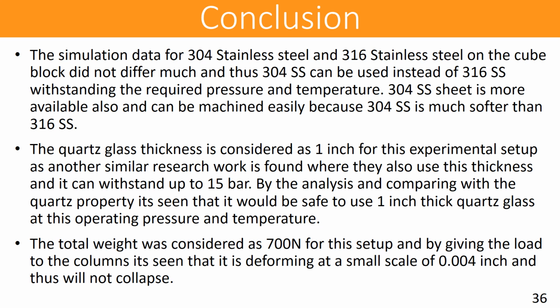As per the optimization of glass thickness, we are going for 1-inch thickness for the window section of the experimental setup, as we found similar research work which can withstand up to 15 bar.